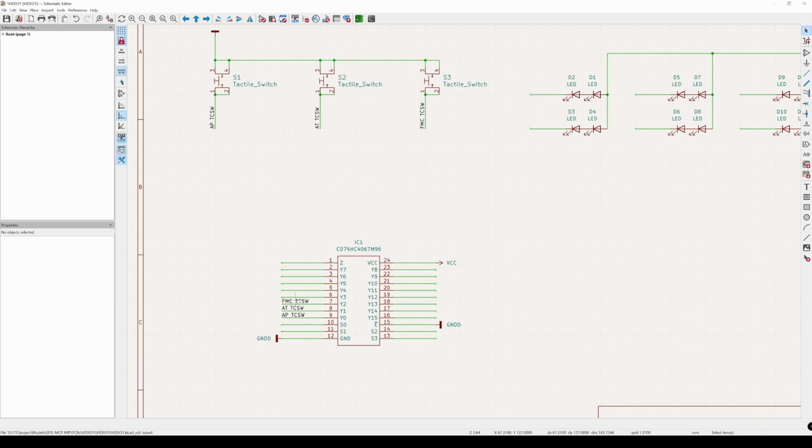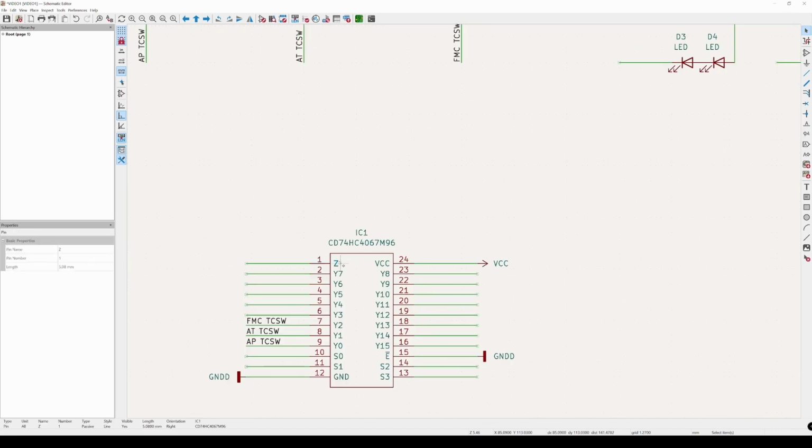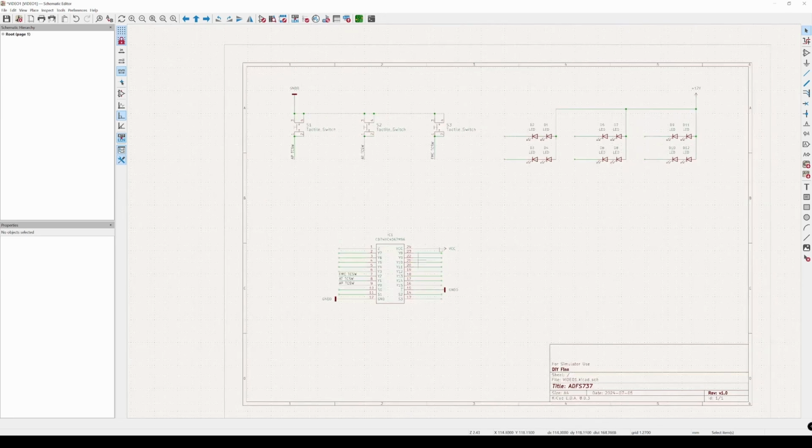But the next thing after the important components are in here is to get the mandatory signal and the address lines connected as well. Now, since I'm going to be connecting this to an Arduino, I need these to be connected into a connector that will be coming off the PCB, and then we'll have wires routed to my Arduino.